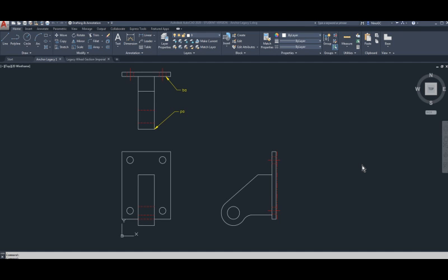Okay, good afternoon. What we're going to be doing today is taking a look at the concept of legacy reuse. We're going to see what happens when we take a drawing out of, in this case, AutoCAD, take the vector elements out of AutoCAD and transfer them into Inventor to recycle or reuse that geometry to create a three-dimensional part. This is the process that can be done when you have geometry that exists, however, it is in a 2D state as opposed to a 3D state.